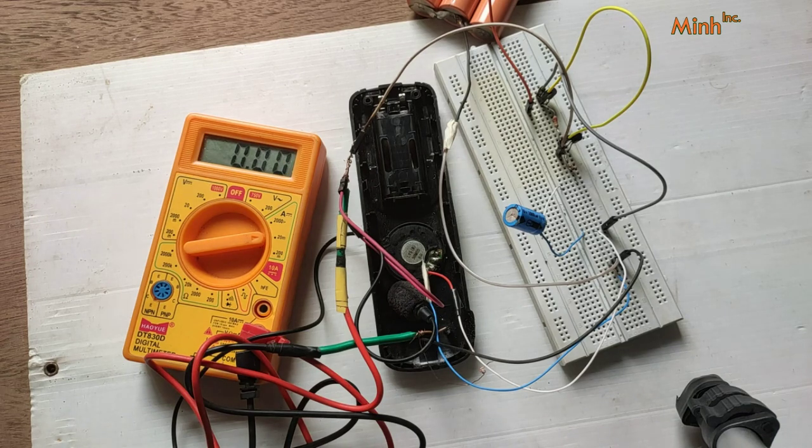Okay, the region we saw now is the active region of the transistor, but since the capacitor is discharging, at one moment it will cut off. So now it is cut off and the capacitor is charging. This is IE, and IE reaches 2.22 milliampere. This is what we have seen. It takes around 30 seconds to charge and 4 seconds to discharge. So the transistor is becoming active and passive, cut off, during this phase.